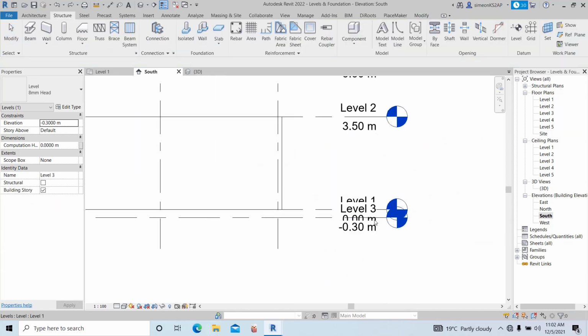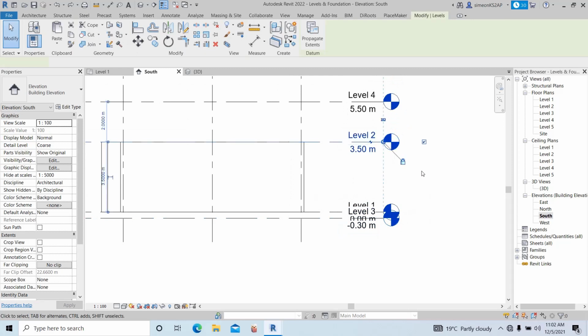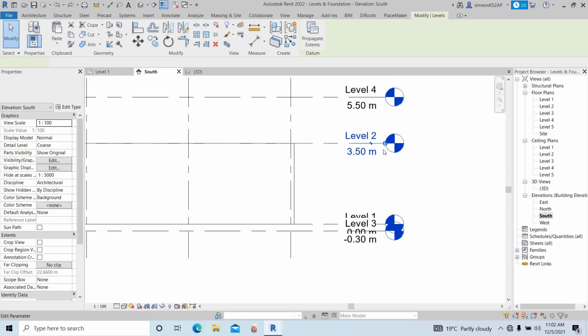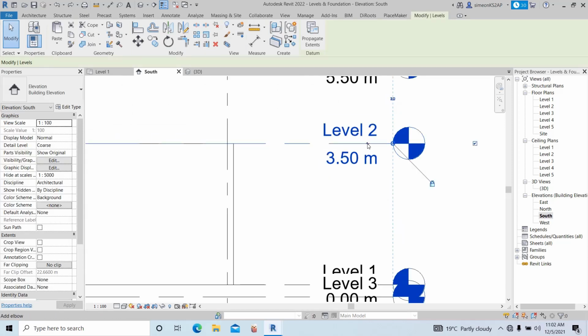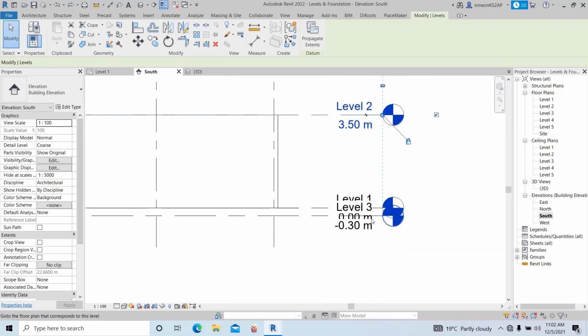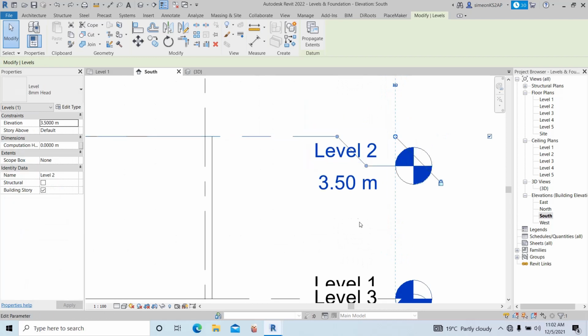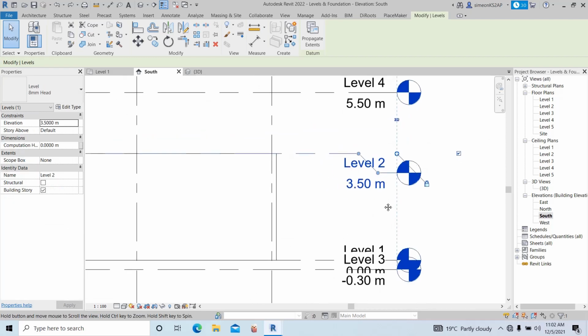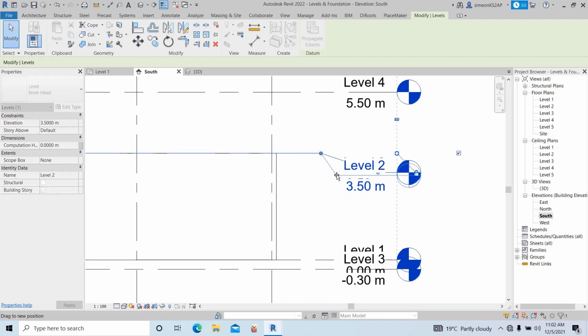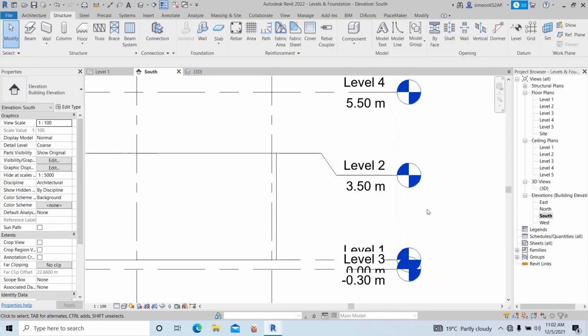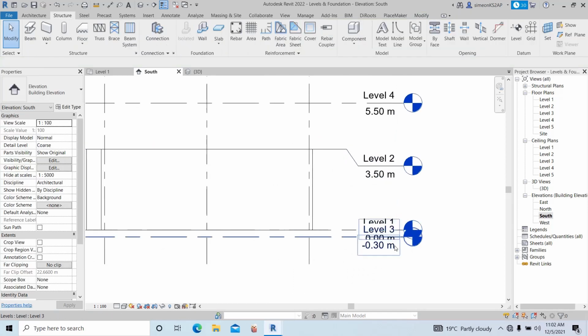I am going to use another level to show you that kind of elbow that I'm talking about. This is the one which is not visible here because it overlaps with the ground level. So if I click on that elbow, I am able to manipulate and change these levels so that it leaves a bit of space between the two levels which are too close.